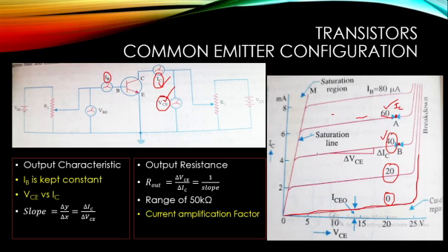So for the same voltage, IC values are different for different base currents. That change can be noticed as delta IC. So we know the change in base current, delta IB, and the change in output current, from which we can calculate the current amplification factor beta, delta IC by delta IB.